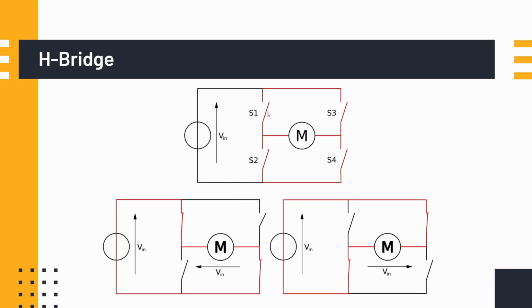But do keep in mind, don't close switch 1 and switch 2 at the same time, because that will short your circuit. Again, our motor driver has protections against these. It has protections against back EMF, which is generated if, let's say, your motor is running, and then an outside force moves it. It's going to generate a back EMF, which could lead to a short circuit. Because typically, if you have a power source and then other power is coming into your system, it does not end well.